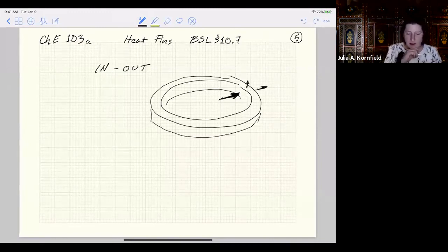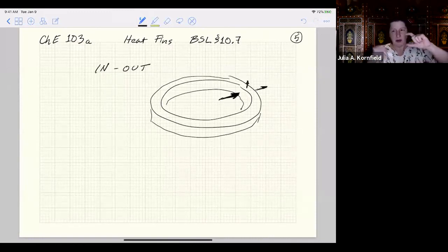And in this case, it's treated a little bit like the electrically heated wire. So in this case, we're treating the conduction as if it's only going in one direction. And we're not treating the two-dimensional character of the temperature field inside the fin, because fins are made of high thermal conductivity materials and they're thin.